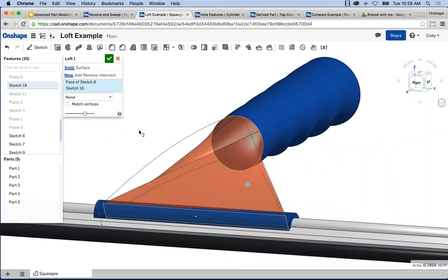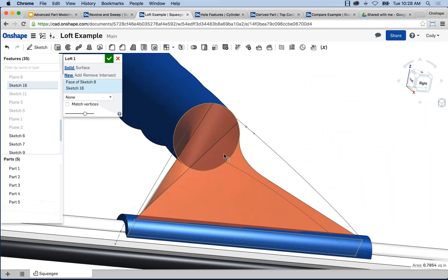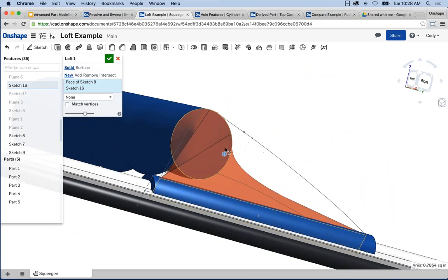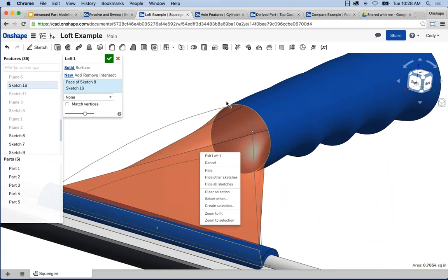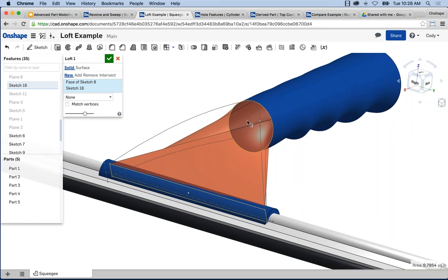One thing to notice is the amount of twist that you see in the loft. Because the number of vertices don't match between the loft profiles, you have to split the number of vertices up. And so a tip, by default, if you just select a face like a circle and something like a rectangle, the odds of it mapping correctly, the points that you want, is slim.